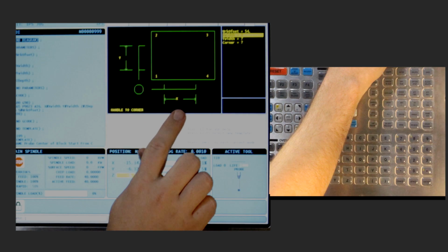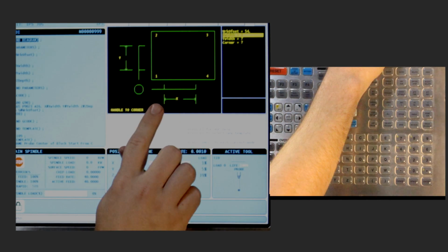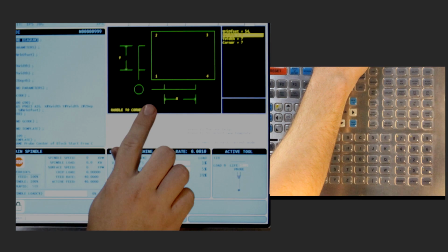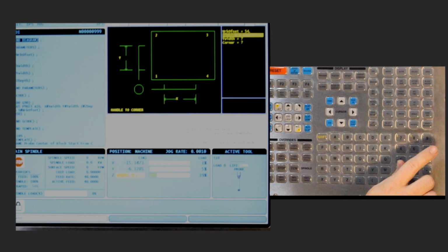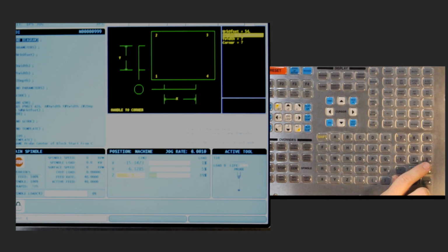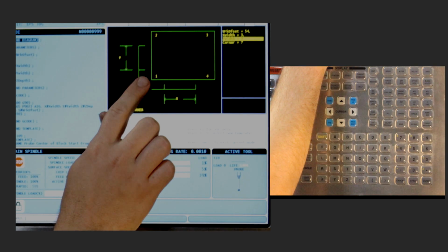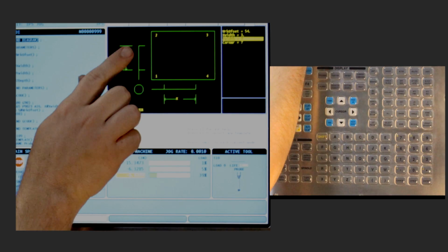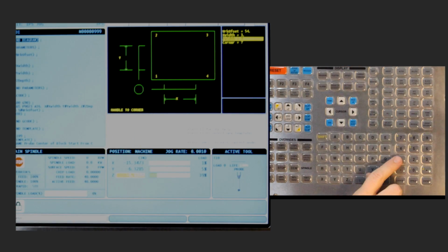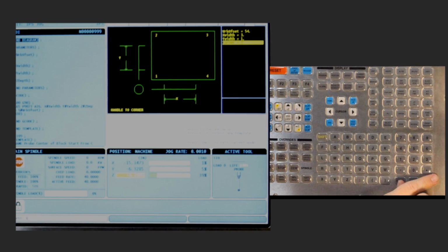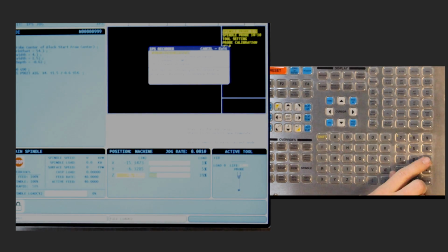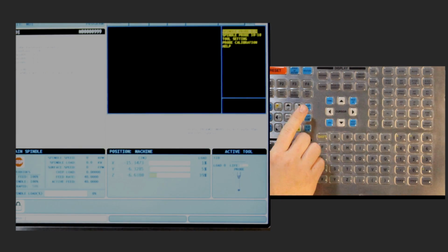Also note, the distances shown are not the width and depth of the block, but rather the distance between probing points. The initial lead-in distance from the corner is fixed at approximately 1/2 inch. You will set the distance from the first probing point to the second for the X and Y directions. For this part, we'll set the X distance between probing points to 3 inches. We'll set the distance between probing points on the Y-axis to 1 inch. These numbers will vary depending upon the part. We'll select corner number 3 for the work origin for this job and output the code to the MDI window.